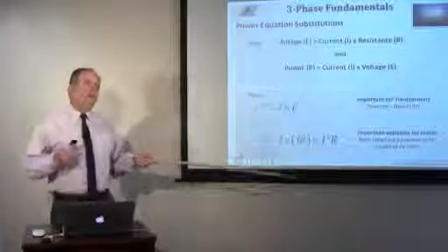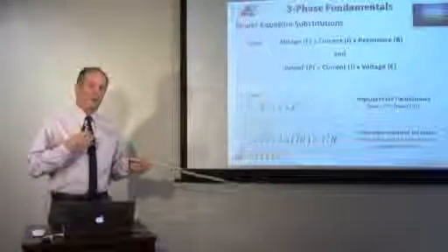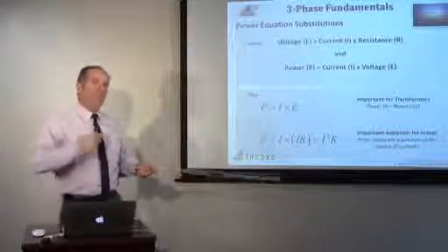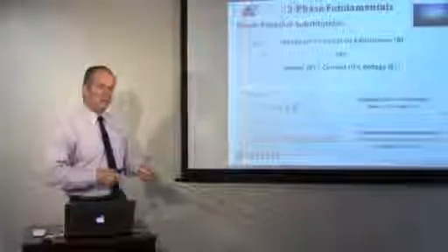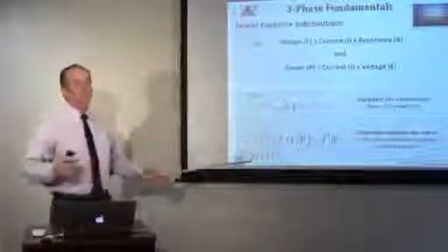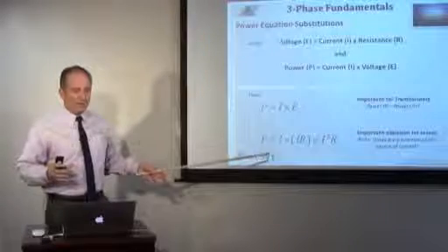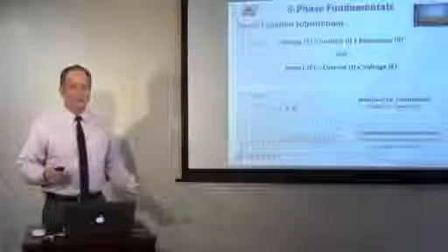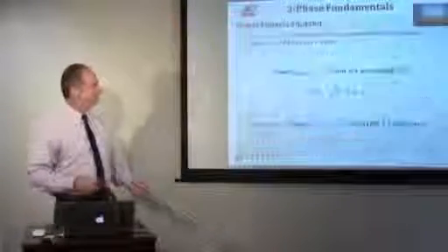So on the input of a step-up transformer, it's low voltage, high current. The output is high voltage, low current. But voltage times current in equals voltage times current out. That's what makes transformers so valuable and useful. And yet we like to know about the I squared R losses because that's what controls our cost.